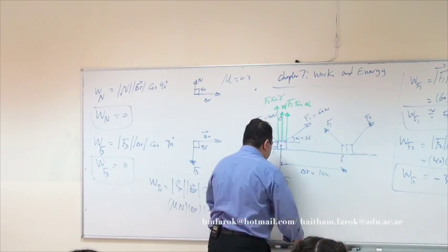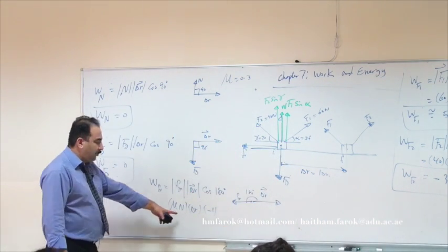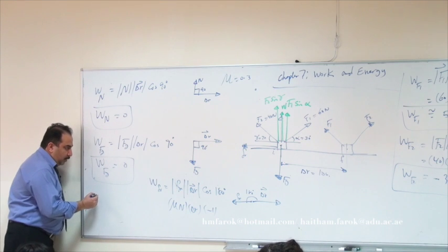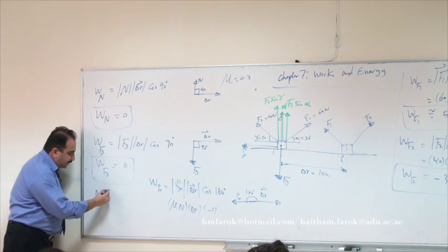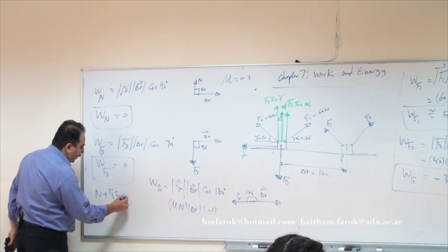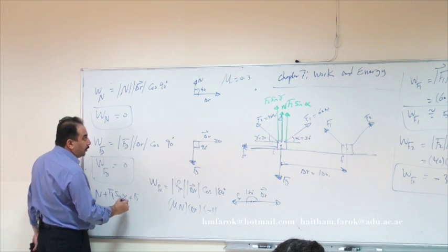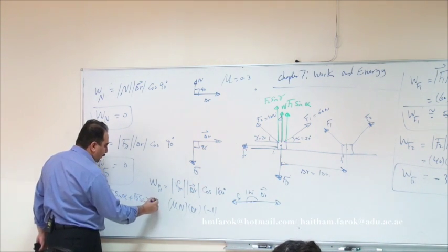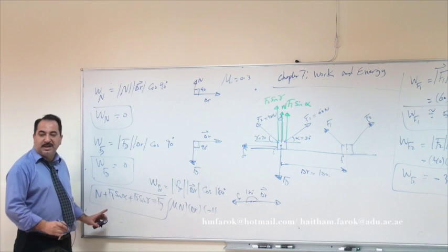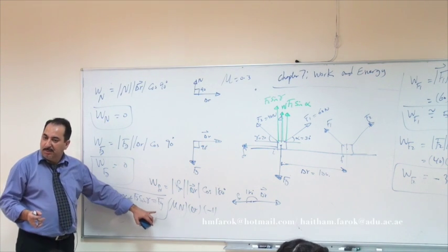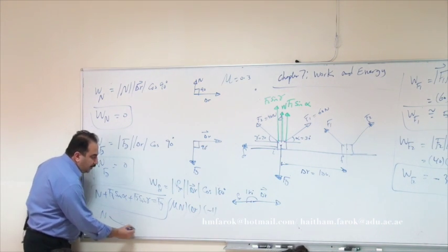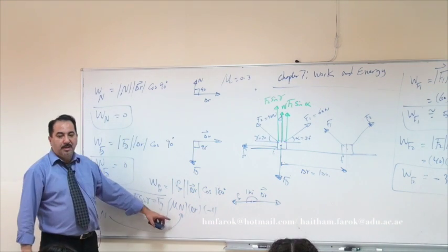Now on the side, calculate that, because you have to put N. So what we have to do is say N plus F1 sine alpha plus F2 sine gamma equal to Fg. So on the side, find what N is equal to, the value, because you have all the values, including the mass. So one of you can calculate N, and then put N here. Multiply by mu. Can you do it?